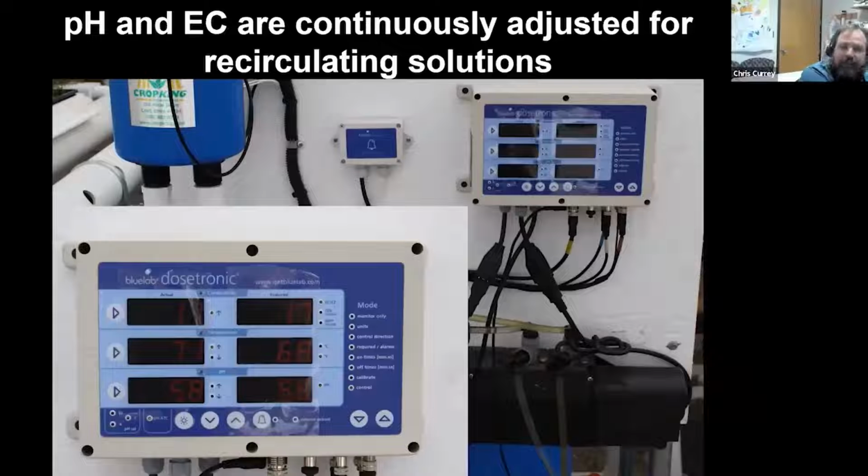We also are constantly adjusting the pH because we want to maintain good micronutrient availability. Generally speaking, we're injecting a type of acid, most commonly sulfuric, but it could be nitric or phosphoric acid. But we inject that acid to lower the pH, again, because we want to keep our micronutrients available to our crops. And as our pH drifts up, that's going to make those micronutrients less available, potentially risking a micronutrient deficiency, which is interveinal chlorosis, rendering our cut flowers unsaleable.